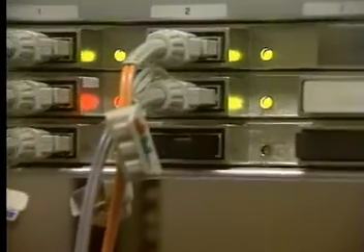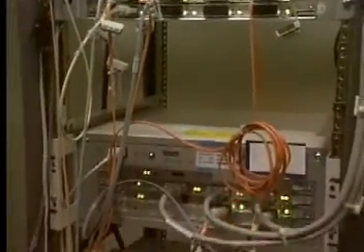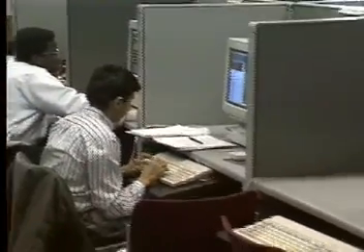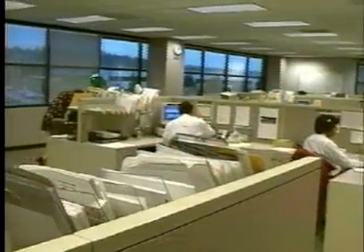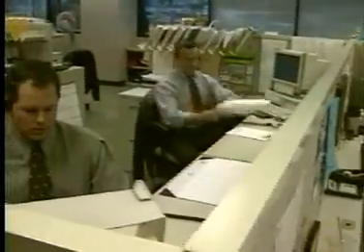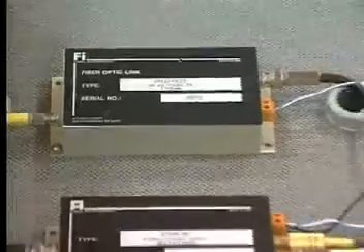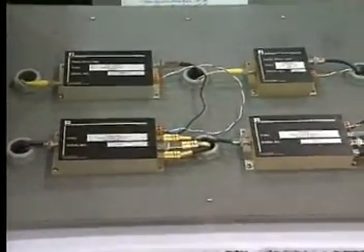The choice between LED and laser will depend on the type of fiber system being designed. For example, edge-emitting LEDs are the optimum choice for LAN systems, including Ethernet, token ring, FDDI, and ATM systems operating up to 622 megabits per second. The output of an LED can be varied in a linear fashion with applied forward bias current, making it ideal for modulating with analog signals.